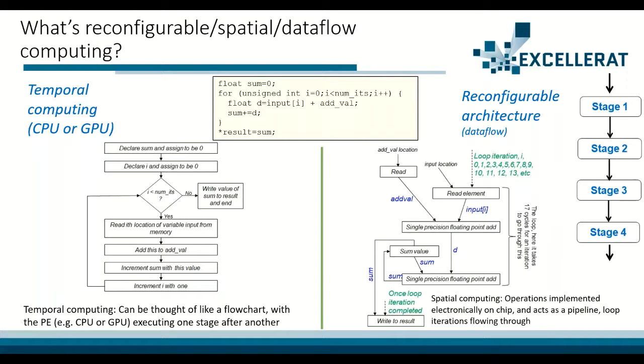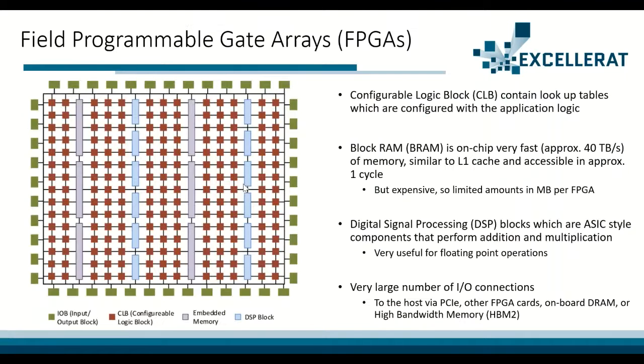Now, when I talk about reconfigurable computing, what that often means, certainly in our domain, is field programmable gate arrays, FPGAs. And if you're not so familiar with these, this is very special hardware because it is directly configurable at the lowest level to look like your application. So all these red things here are configurable logic blocks with lookup tables in that can be configured, as I say, to look like your application.